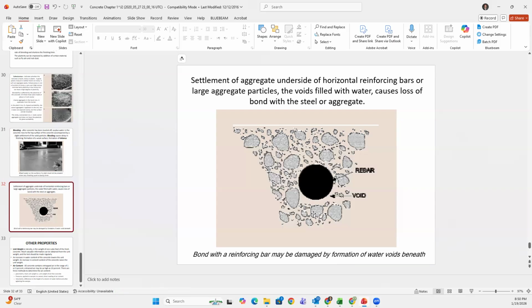to work harmoniously with the rebar. If the rebar is not attached, this is where the rusting is going to happen. This is where the water is going to pile up. This is where the air is going to get entrapped. As a result, you're not going to have a strong reinforced concrete slab or building, because the concrete has not grabbed hold of the steel properly, or this area is full of sand.